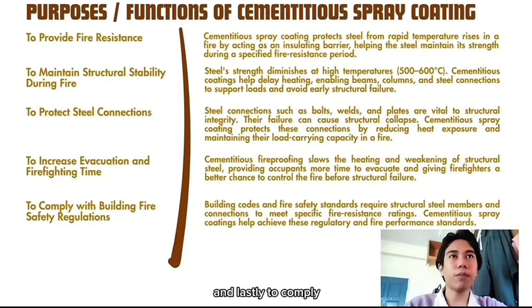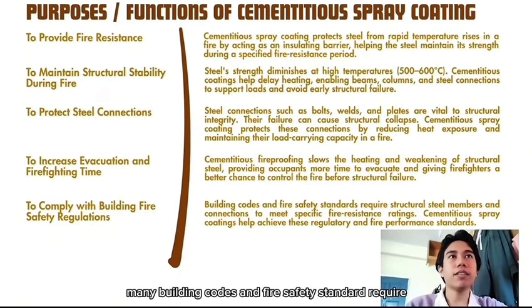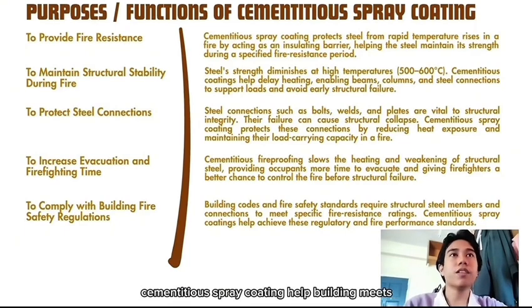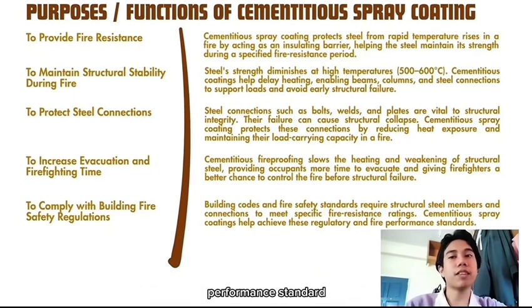And lastly, to comply with building fire safety regulations. Many building codes and fire safety standards require structural steel members and connections to achieve a specific fire-resistant rating. Cementitious spray coating helps buildings meet this regulatory requirement and fire performance standard.